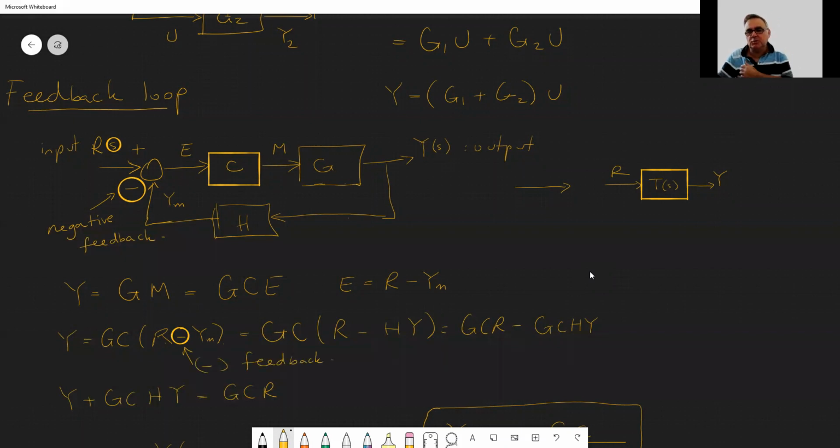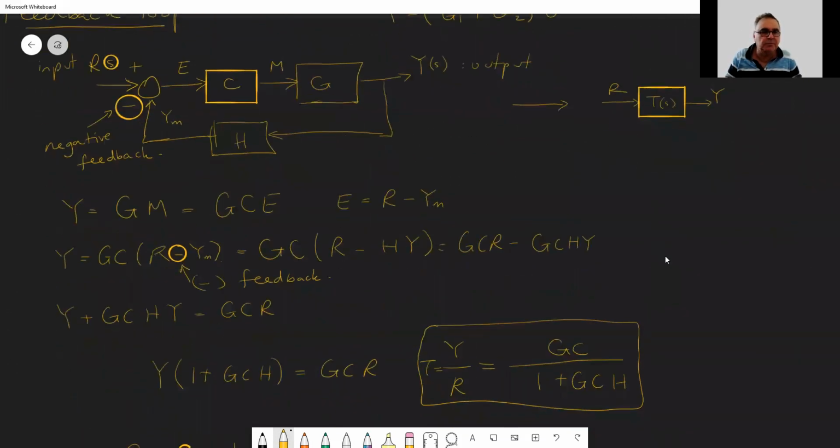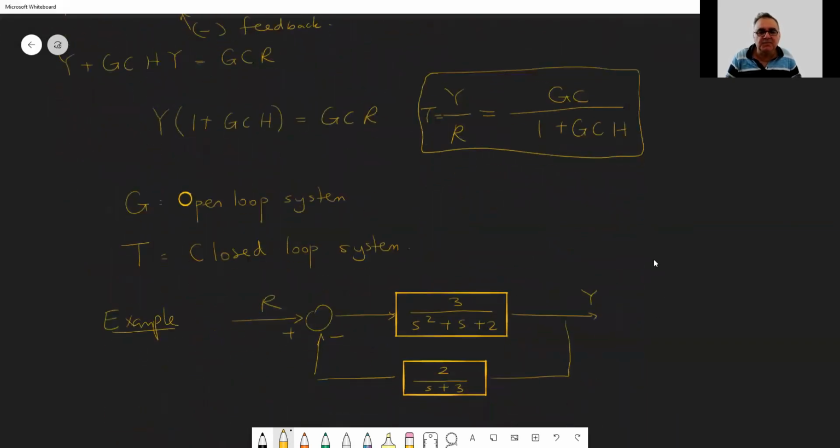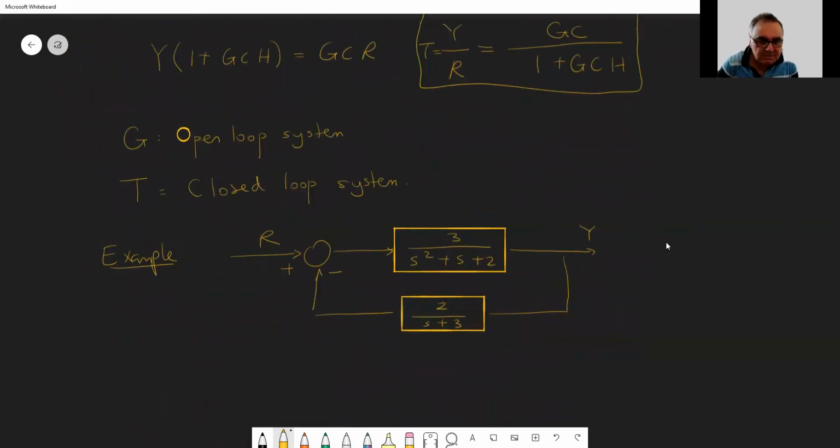Negative feedback, you know, the name is negative, but negative feedback is something good. It usually stabilizes the system. So don't fall for it. Positive feedback is something not so good. It usually destabilizes the system, okay? That minus sign indicates negative feedback. Negative feedback has a stabilizing effect usually. It moves the poles to a more stable region most of the time.